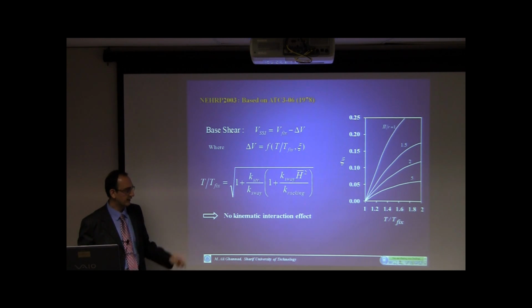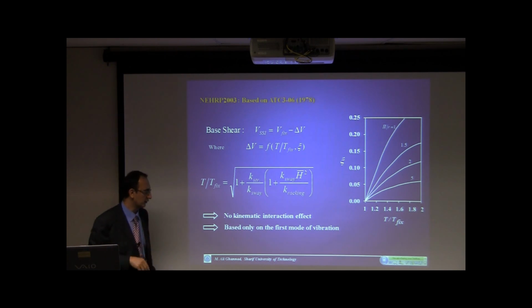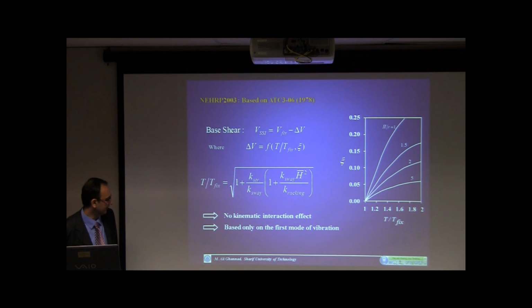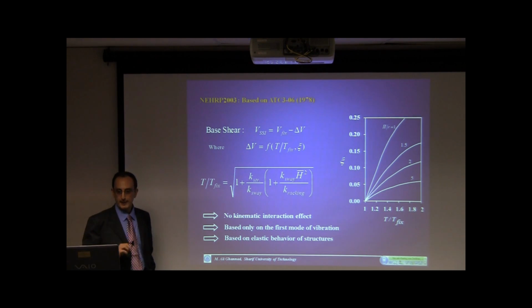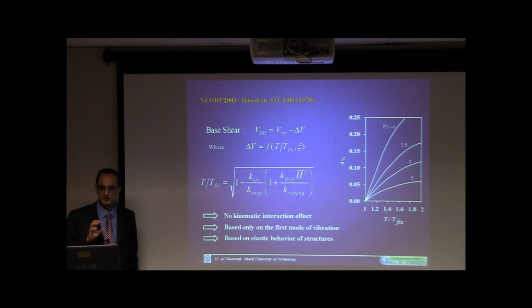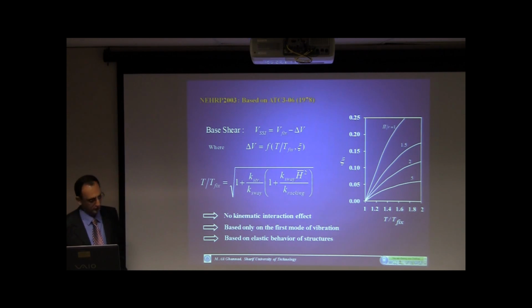There is no kinematic interaction effect addressed in these regulations, and this is based on the first mode of vibration. It means that it is considered that the main effects are on the first mode and the effect on the higher modes is neglected. And most importantly, it's based on the elastic behavior of structures. When you estimate the response of the system with its period and damping only, it means that you are estimating the elastic response of the structure. That's why we know that structures go to inelastic behavior during real strong motions.